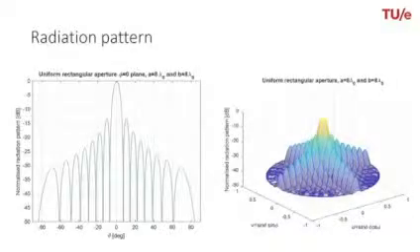Now, besides two-dimensional representations, we can also have three-dimensional representations. So again, we use decibels, but here we also introduce UV coordinates, where U and V are related to theta and phi and are very convenient to use. The circle that you observe is what's called the visible space. So the circle is indicated by the region where U squared plus V squared is smaller than 1, and that's, as I said, related to the visible space.